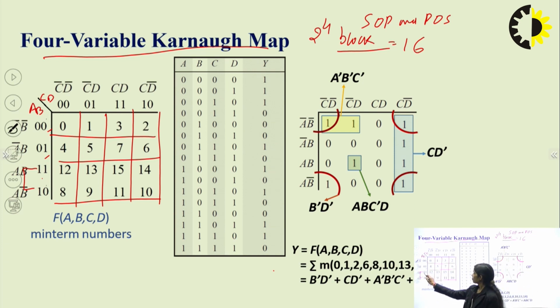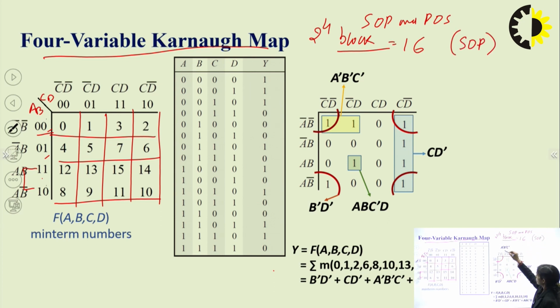So this can be interchanged like this. Also this 00, because we are assuming this as a min term, we are taking sum of product terms here. So this 00 can be represented as A bar B bar, this is A bar B, this is AB and this is AB bar. If we can write CD here, 00, 01, again 11 will come here.